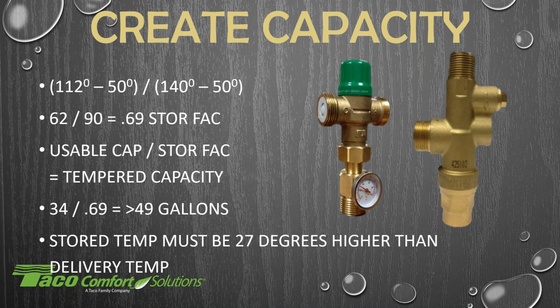You need to see a 27-degree spread between the delivered temperature and the stored temperature, so you get the thermostatic element of the valve to operate properly. When the spread gets too small, too close, you won't get that full operation of the valve. And what we have found is that you get a little sandwiching of the water temperature being delivered to your fixtures, meaning it's warm, then cool, then warm, then cool, then warm, then cool. You feel a little bit of sandwiching because the valve doesn't have that full opening and trying to control that water temperature. It's always trying to be on the safe side so it doesn't send too hot of a water out, but then it starts to close down on itself. So you want to see a nice spread between.